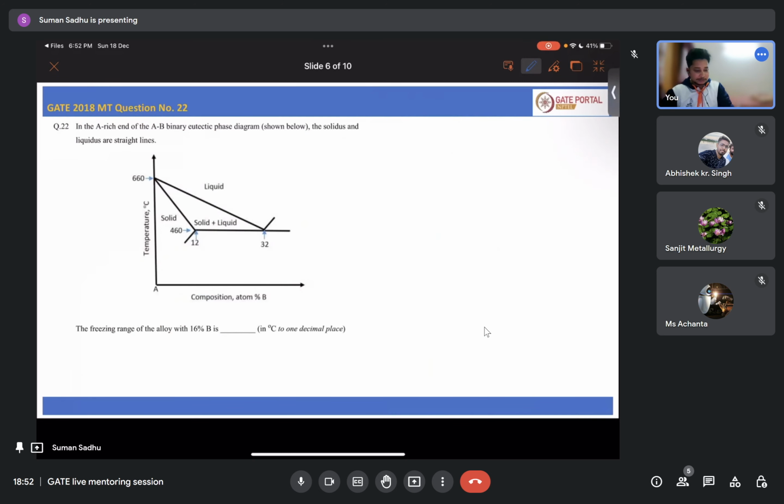Like, you have two alloys. Let's say this point is 0.025, and now you have two alloys. One is, sorry, not 2%. It will be below 0.8. So let's say 0.2%, and this is let's say 0.4%. Now you are cooling it down slowly, okay? And now after some time you are at this temperature, just below your eutectoid temperature. So for one case you are here, for another case you are here.